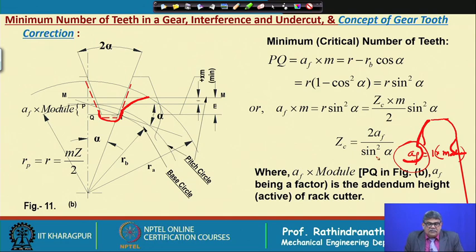If there is an undercut that needs to be modified, it is possible that we can modify the teeth and avoid this undercut. In the case of modification, say for example, if I consider this tooth itself, we are not allowing the cutter to go to the full depth, or we can maintain a depth at least for which this involute will be generated from the base circle. Say let us consider this is the base circle.